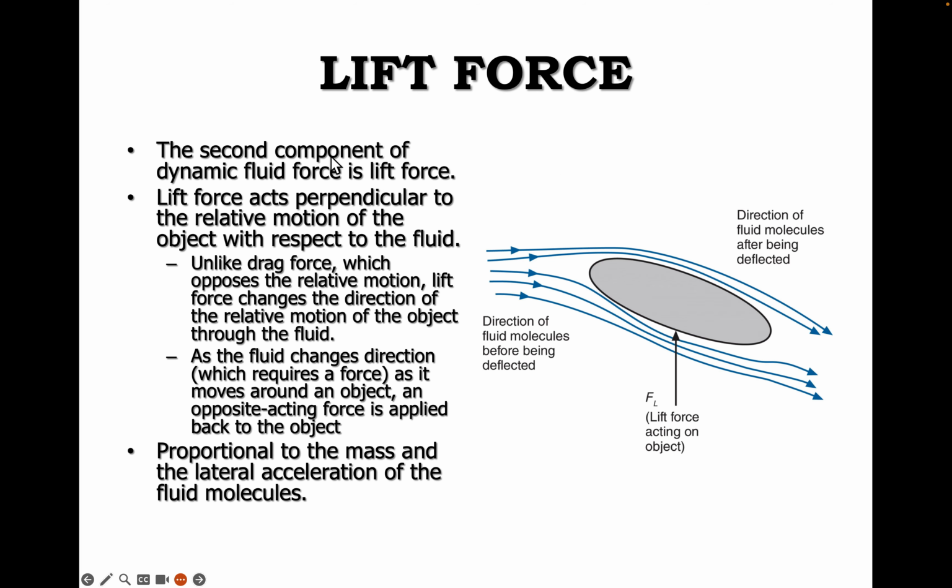Now, the second component of dynamic fluid force is going to be lift force. We've been talking about drag force this entire time. Let's talk about lift force, okay? Here's what's important. Make sure you star this or something along those lines. Lift force acts perpendicular to the relative motion of the object in the fluid, okay? So in this particular case here, lift force would be this upward arrow in this particular diagram.